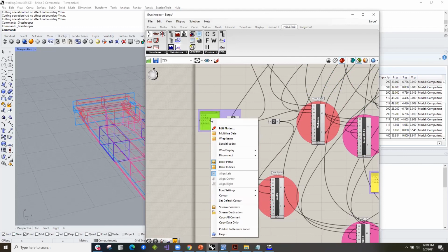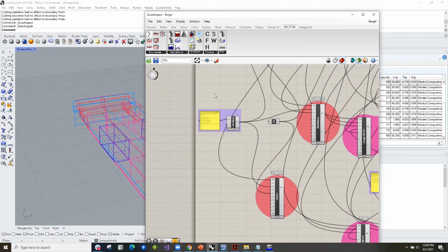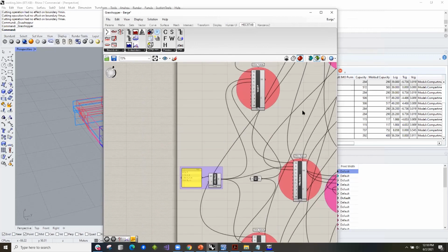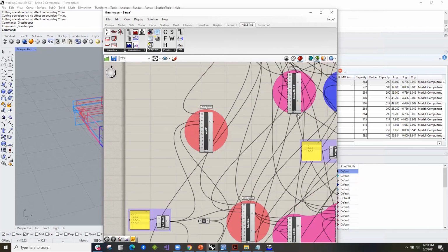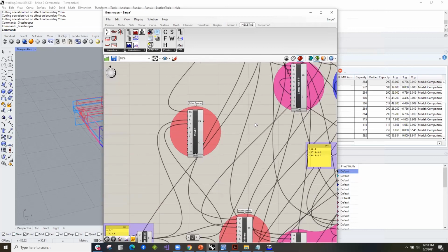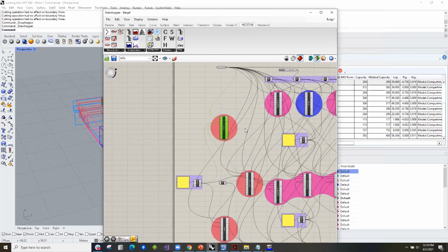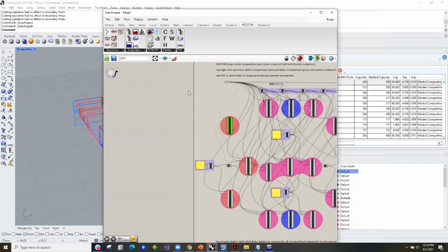That's okay. If you've never used Grasshopper, I think I was a bit doubtful when I first started looking at the Rhino plugin. I wasn't even thinking about Grasshopper. But the more I used it, the more the wires can get a bit much visually for bigger models. So if you're doing bigger models, I would tend to break these up into smaller Grasshopper files, just because of the wires.